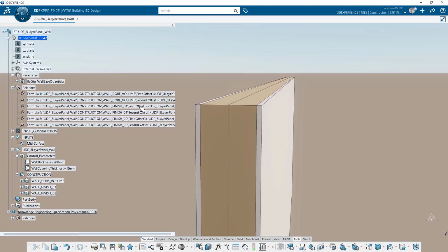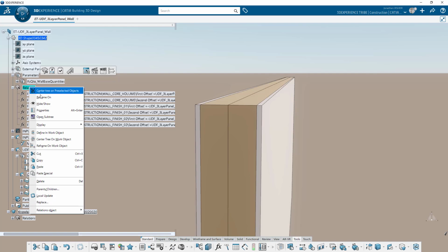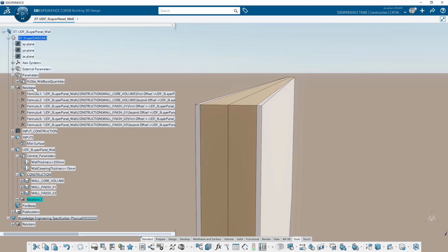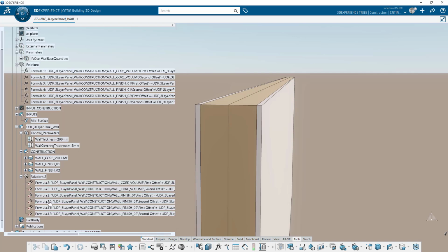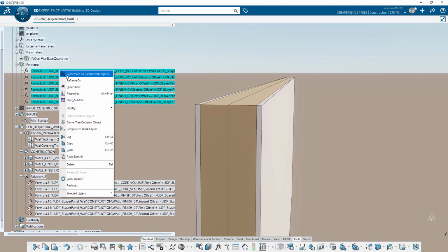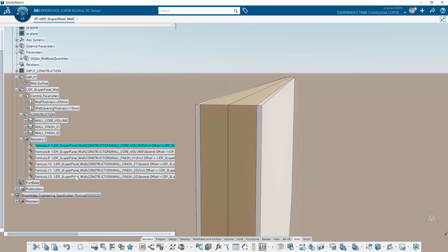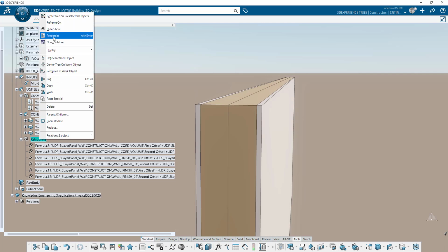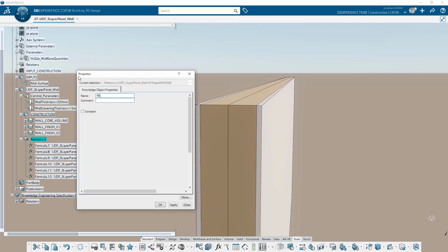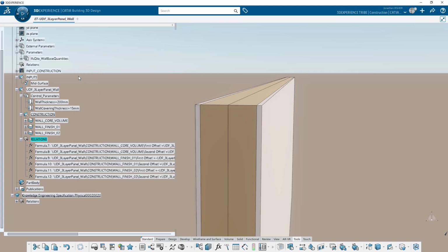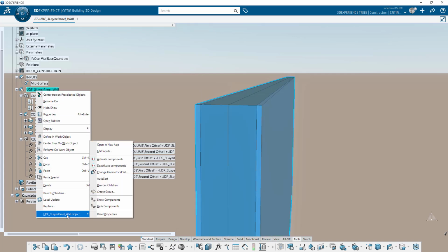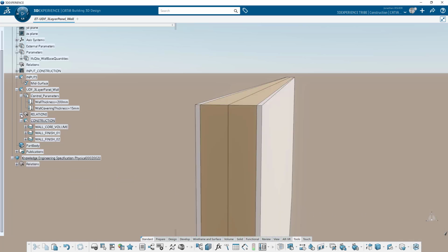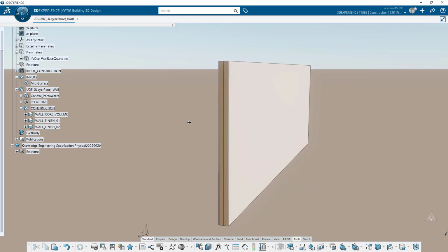In order for this UDF to maintain its parametric relationships between the formulas and the geometry, especially those volumes, we need to move the relations from the exterior of that geometrical set into the interior. We'll do that by copying the entire relations set, pasting it into the geometrical set, deleting the original relations, and then activating the duplicate relations, those duplicate formulas. And by doing that sequence of operations exactly in that sequence, we'll be able to maintain the formula relationships between the parameters and the geometry. So with that done, we're good to go.